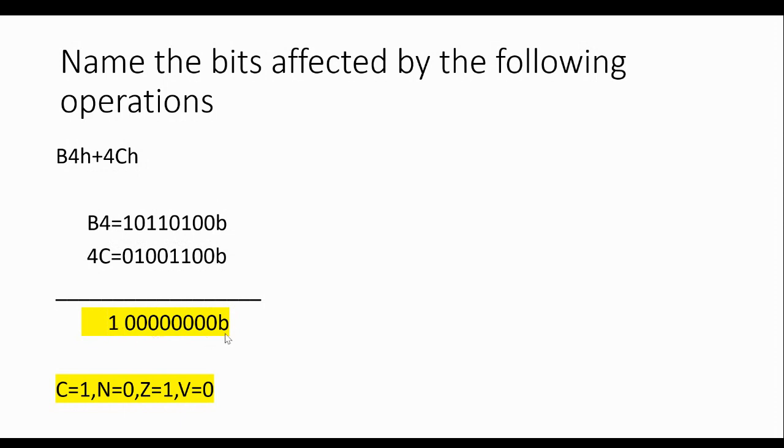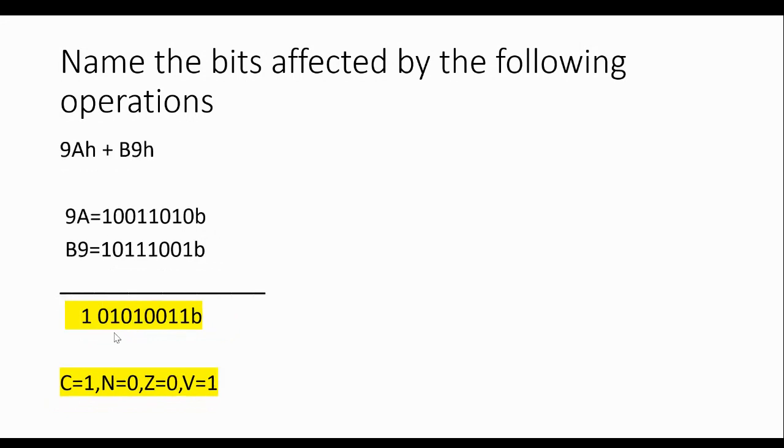Now in this case you have zeros, so the 0 flag will become set. V: 1 and 0, it's not the same, so you get 0. Negative is 0, because the most significant bit of the answer is 0. And the carry is actually 1, because after you have a carry forward, you get a 1.